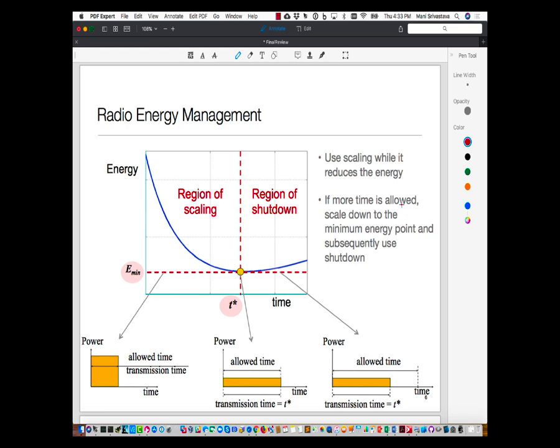And therefore, in terms of energy per bit, which actually makes it through in expected value, you will come out behind, right? Because a lot of your bits are just getting lost. So you may actually be better off slowing things down. And by slowing things down, you gain some time, which you can now utilize towards either using less aggressive modulation or doing more error coding. So that's really the play that is happening. You need to think in terms of the information I'm getting across, not simply the bits appearing over the channel.